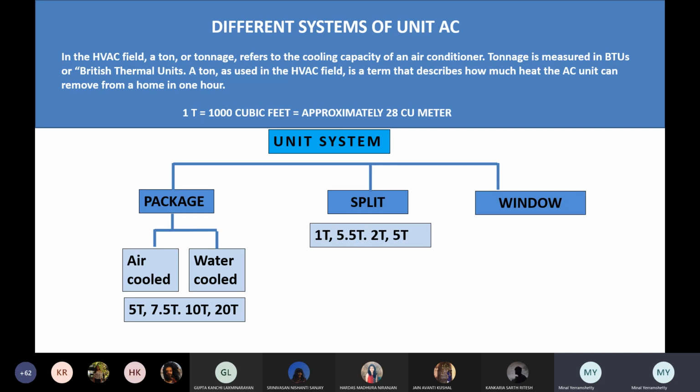Also, when I have a condenser sitting there, as well as that compressor, it's going to make noise. So I have to have acoustical treatment. I have to see to it that the placement of the package unit is in such a way that it does not matter to me when I'm working there. Otherwise, that humming sound is going to affect my productivity. The third thing is drainage, because the evaporator is going to condense and it's going to shed water.